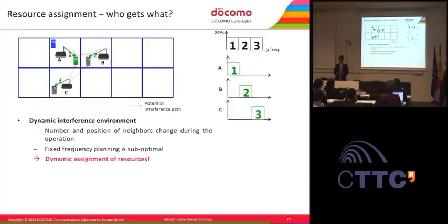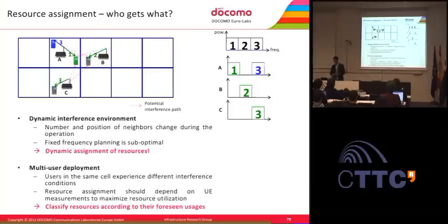Here we have each cell using one component carrier. You can simply do this by sniffing your environment. As I said before, the home node B has a downlink receiver. So just by listening to its environment, it can assign a component carrier which it sees is experiencing the least interference. But then you again want to reach the situation where cell A is using 3 because component carrier 3 is not causing any interference to the other cells.